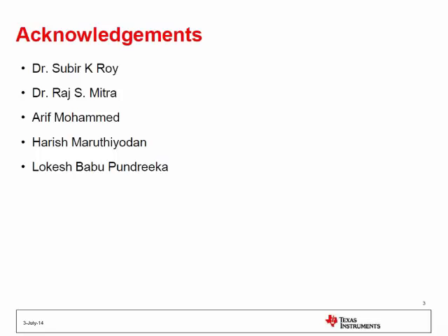What do I mean by FP? I think we have been talking about FP. Basically, what I mean by FP is nothing but a formal analysis which helps to prove or disprove that the design is actually meeting a formal specification. This is a very loaded sentence, which is why I've split some of the terms here. The design here is basically the design under test. It is usually the RTL. Here again, the stress is on the word usually, because you'll also see some of it being software like C, or even high-level abstractions, not necessarily the RTL.